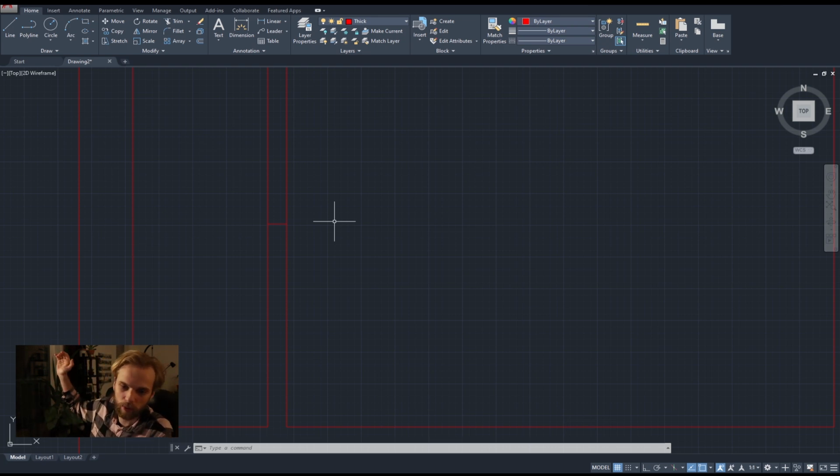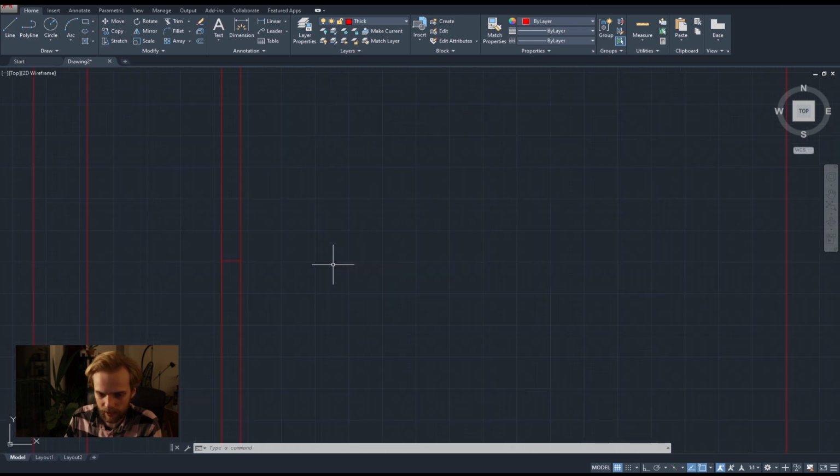The height of the door is usually in between 2.1 meters and 2.2, depending on what kind of door you're using. But usually what I like to do is do 2.2 meter height doors and add, if I need to, framing inside, so it kind of eats up a little bit of that height. Either way, we have the line segment.